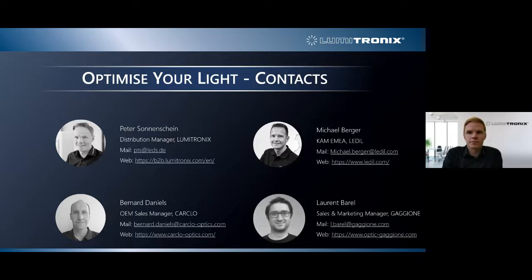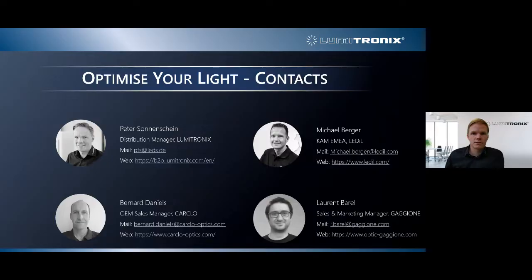So the straight answer is yes, we usually see more color deviation outside of the D10, the FWTM, meaning the beam angle corresponding to 10% of the maximum intensity. There is always a lot going on in color mixing outside of this.